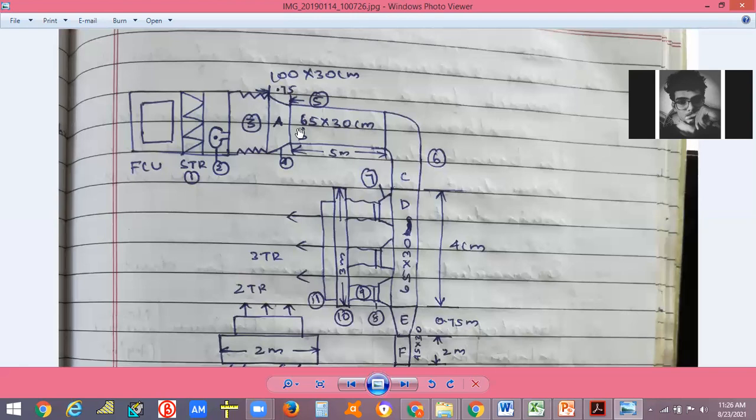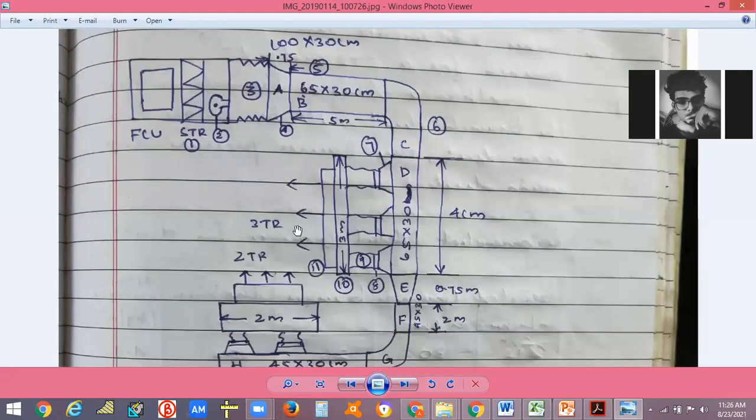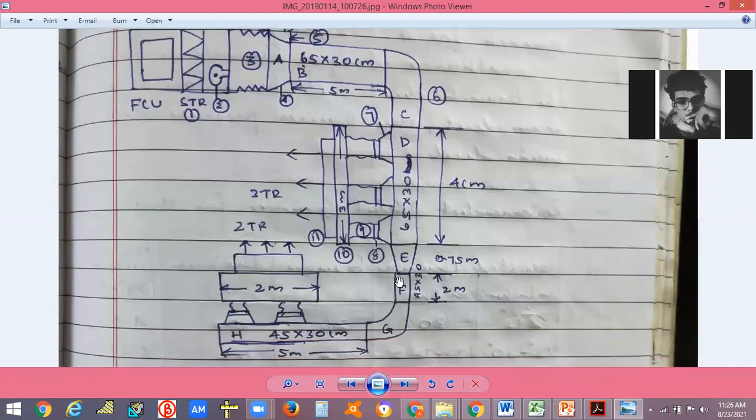Now it is going through the elbow. It is spread into 3 different flexible branch ducts, and the 10th one is the plenum box, and it goes through the grill. Here this is 3 tier, here this is 2 tier. Again here reducer, duct, elbow, here the duct is divided into 2, and goes to the plenum box and goes to the grill.